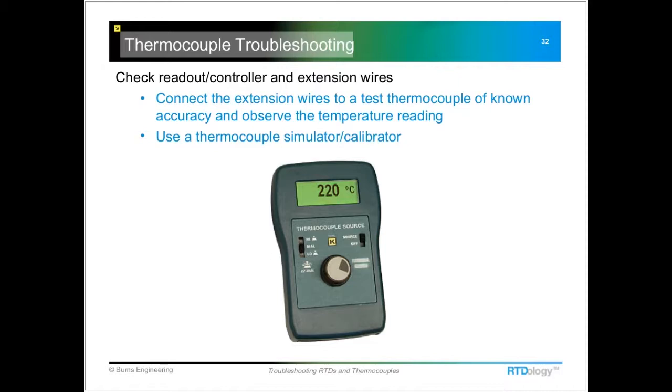Typically, when the thermocouples are manufactured, the wire is tested for homogeneity, and that's when you really know what accuracy the thermocouple is going to have. If it's been used in the process, you're not going to really be able to go back and retest it. It almost has to be done by comparison with another good thermocouple or some other temperature measurement method.